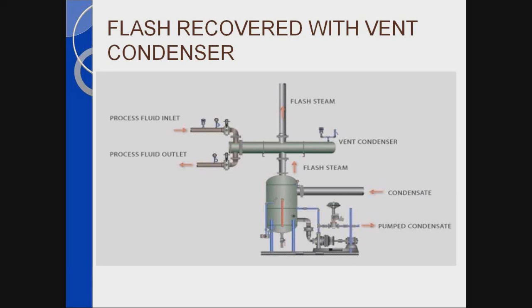Now, condensate can be pumped, as is shown here, through variable speed drive pumps or control valve pump applications like this, maintaining level in the tank. But remember, the same philosophy in condensate tanks as we apply to flash tanks uses the same calculations. We want separation. We want the flash to be separated and vented at very low velocities. I would say 95% of the vent condensers that we put in have less than a 6-month payback. Venting flash steam is so costly to the plant today.